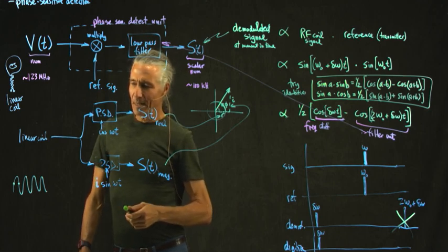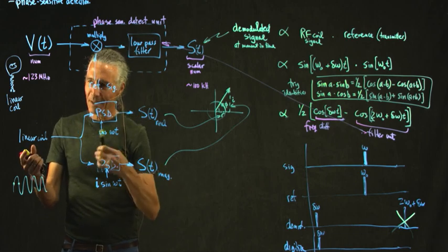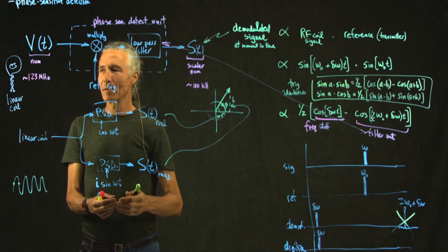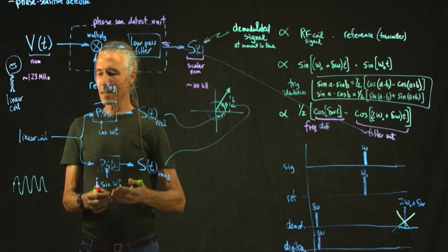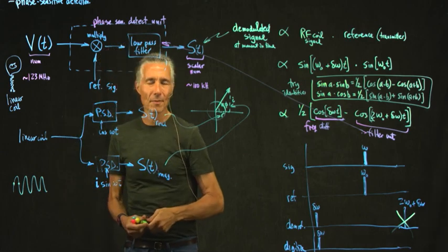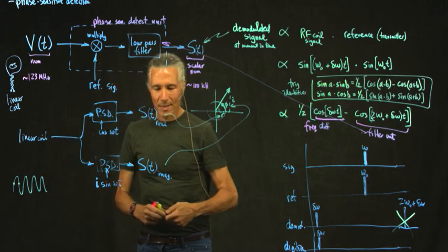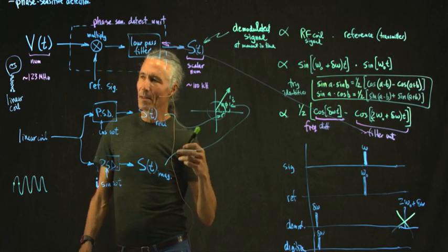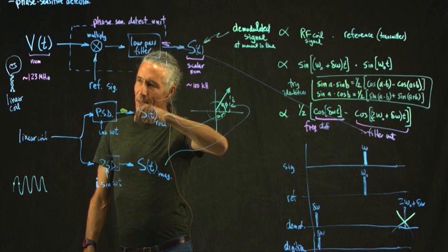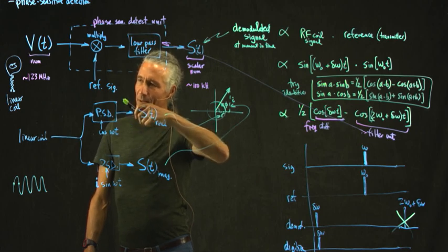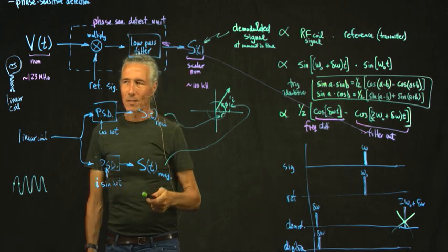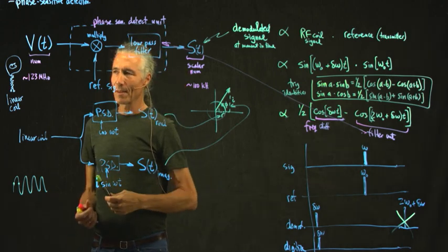Now, when you first look at this, you've only got one number, so it's just like, where does the extra number come from? Well, the extra number comes from the transmitter. So the transmitter adds information into the single signal to make this double signal. And that's fundamentally how you get the phase angle, and you distinguish, say, 90 from 270 or 0 from 180, because you've got this additional information from the transmitter.